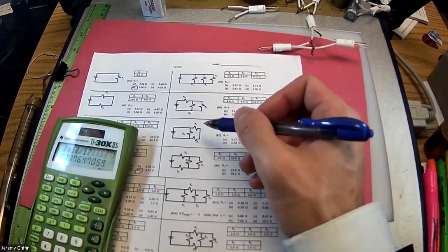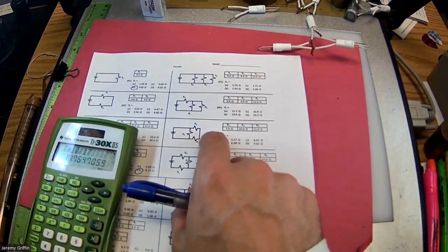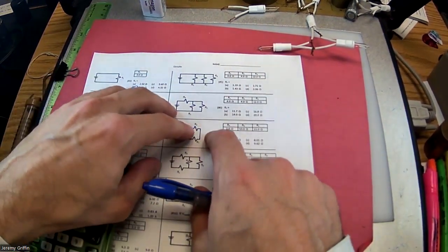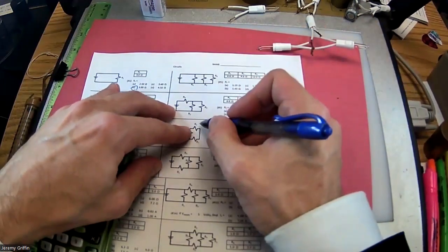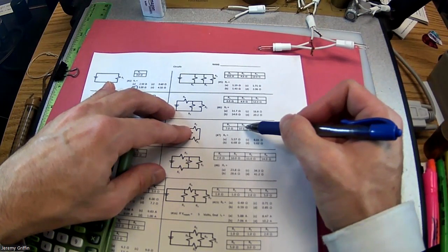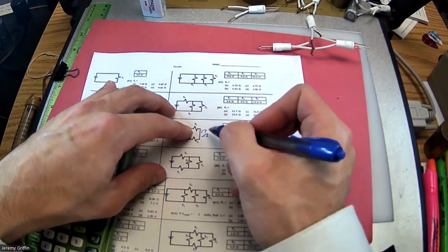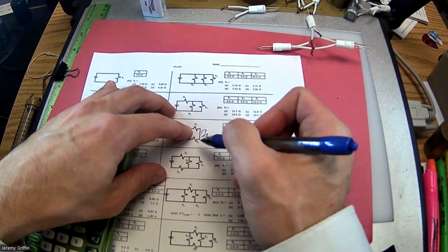Now these are starting to get more complicated. The process always goes like this: you find your voltage source, you fly over to the opposite side of the circuit, and you start finding equivalent resistances and work your way back towards the source. So the fact that these 2 guys are in series, what is that? That's 10 ohms and 7 ohms. That's like 17 ohms, right? So it's kind of like there's a single 17 ohm resistor there, okay?